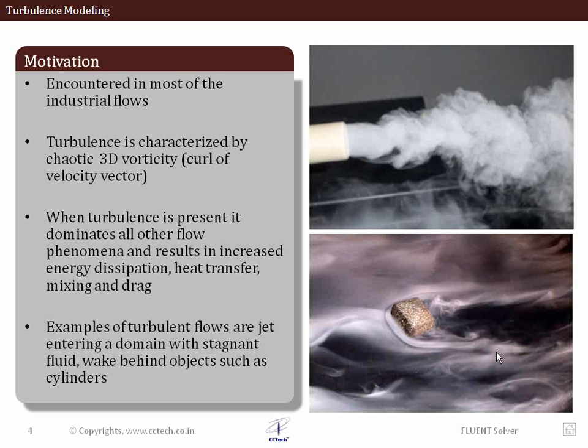Well, turbulence is encountered in almost every walk of life. Whenever there is a flow, it's very hard to encounter a laminar flow. If you are familiar with laminar flow from the fluid mechanics lecture, turbulence is a flow which is highly chaotic. It's a three-dimensional phenomenon, not a two-dimensional or one-dimensional one, which means that the curl of the velocity vector, del cross v, is non-zero.